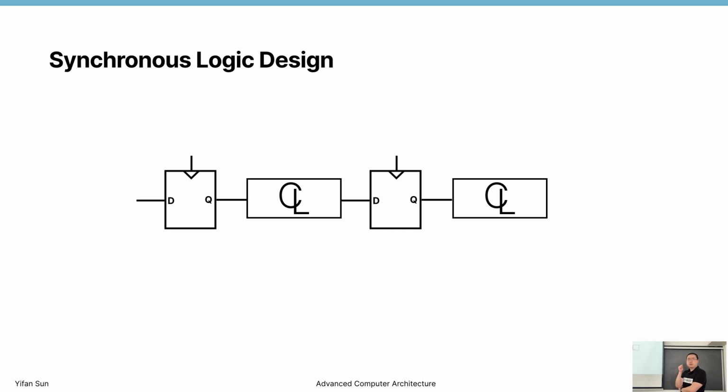The quick answer is we should never have a fluctuation at the time a rising edge arrives, because the fluctuation comes mainly from the delay of combinational logic.